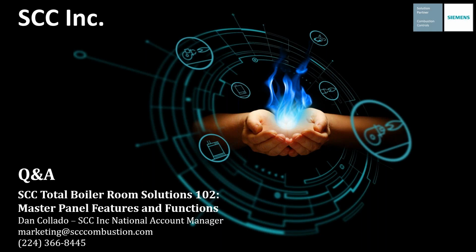Yeah, thanks, Alan. No, the master panel comes only as a complete UL listed panel. The majority of master panel applications are new installations, or they're replacing installations of existing lead lag panels, and they're going to be mounted separately on the wall. And as a result, the only option for the master panels are complete enclosures. We have NEMA 1, NEMA 4X, or NEMA 12 as an option, and you can actually add cooling fans to any of those options as well.